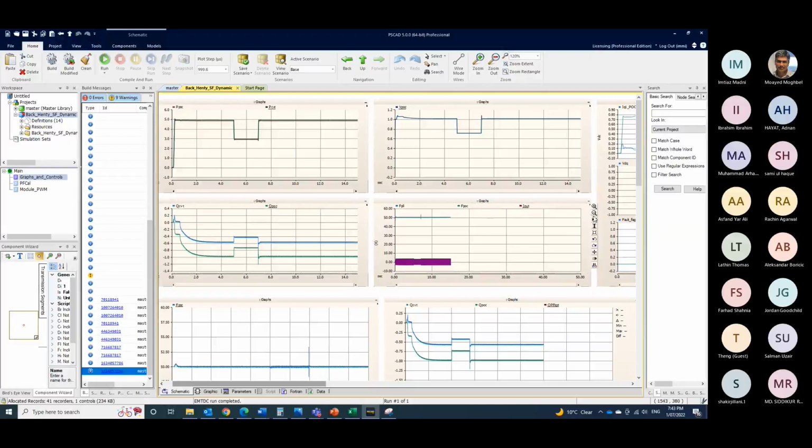Okay. I just wanted to show you this fault ride through scenario. Obviously, if we want some time for stabilization, that's where we normally model for a longer time, and we can implement the fault somewhere after it has stabilized. Yeah, if we do some initialization, then we can apply the fault, let's say at 2 seconds. Yeah, fair enough. Thank you.